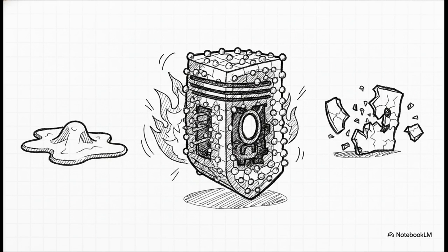When you're explaining this, your magic keywords are hydrogen bonding and high crystallinity. Those strong hydrogen bonds provide the thermal stability to survive engine heat. And because that crystalline structure is packed so tightly, there's practically zero free volume for fuels or solvents to penetrate. PLA would literally melt in there, and ABS would just degrade from the fuel.